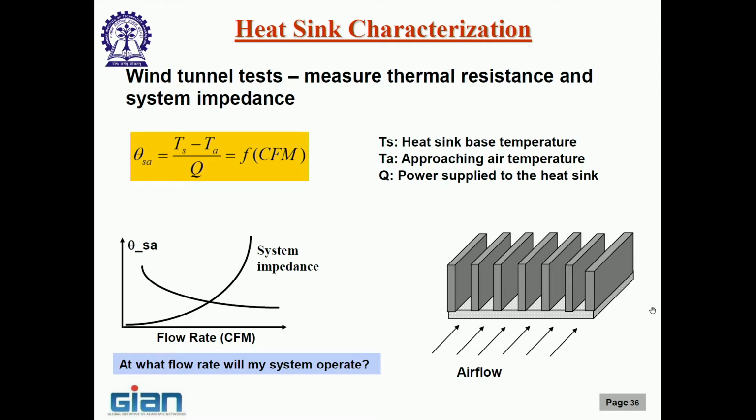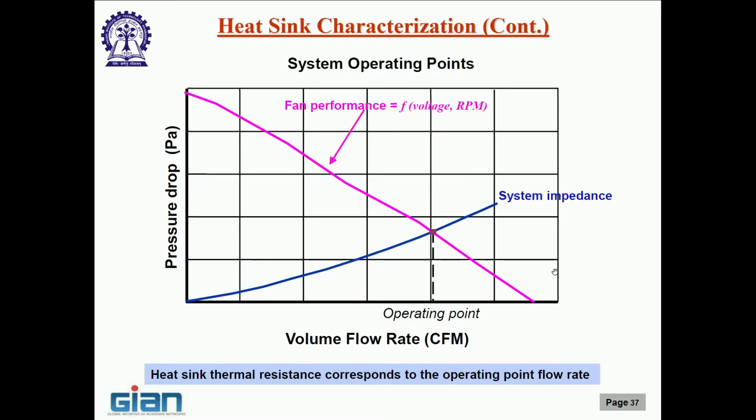Let us take a very simple example of the one that I am passing around. Forced convection, I have a plate fin heat sink, parallel plate, though generically you can use this for any other type of heat sink as well, a pin fin heat sink for example, and I have airflow going through this. Clear? So, how am I going to characterize these? The first thing, coming to your point, is can I indefinitely keep on increasing the number of fins, which essentially means I will indefinitely keep reducing the fin spacing. Yes, surface area will go up, but your h will go down.